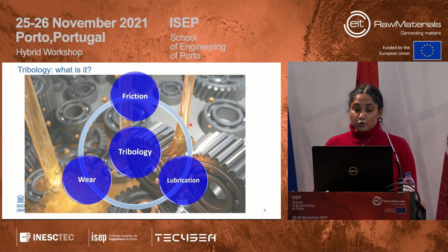Now, if the oil is too viscous, the gears do not move, there is high friction, and your car probably doesn't work. But when the friction is too low, there is another problem, where gears come into contact with each other and wear. So friction and wear are not always negatives. There are positive effects as well. For example, friction is necessary when you walk on the floor, and wear is necessary when you want to machine a component, that is, cut a sample or make specific shapes.